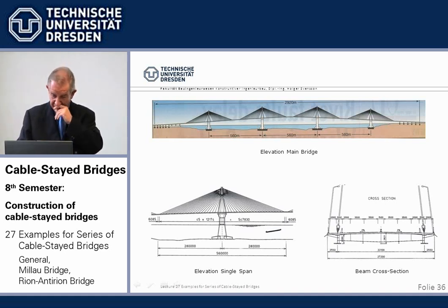Now, each unit consists of a solid, rigid pier with a total length of 560 meters beam supported by stays. We have here the cross-section. I would nearly say an American cross-section. That's the way we designed our bridges in the US. Open cross-sections, not boxes, and a composite bridge deck, because they also have a problem with welding, apparently, in Greece. So that is the most economic solution.